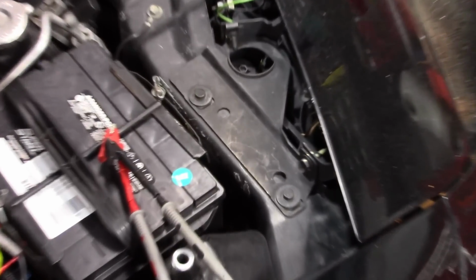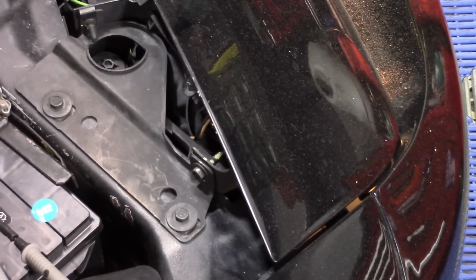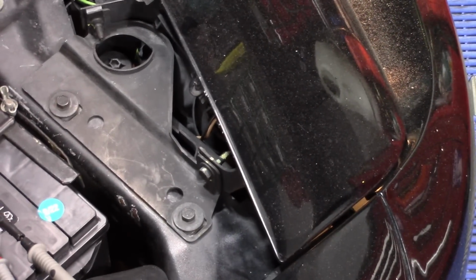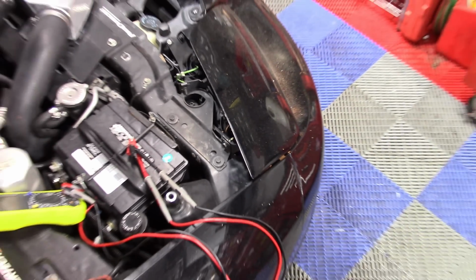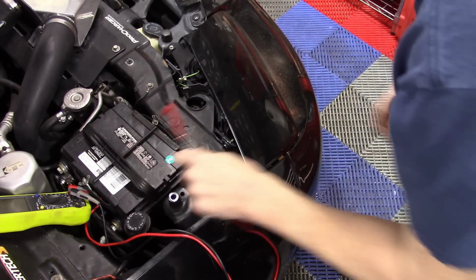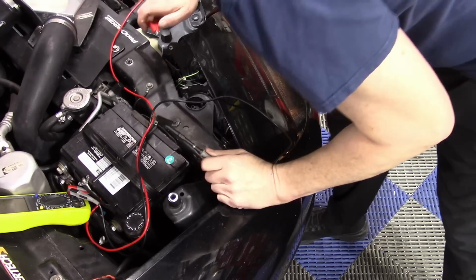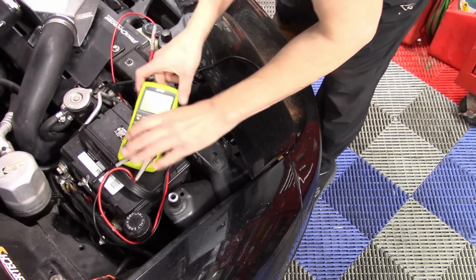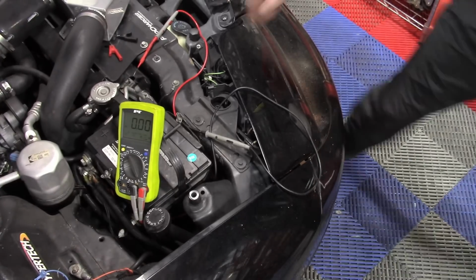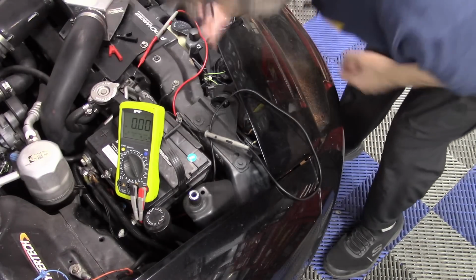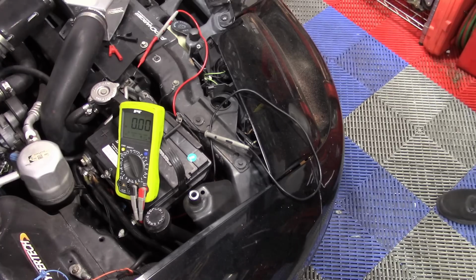Okay, it actually worked. If we look real careful, we can see some light from the headlight showing through. So the headlight is on now. I'm going to measure voltage drop across my headlamp bulb. What I'm going to do is take one lead of my multimeter. Let's get the multimeter in there. The easiest things to reach are going to be this brown wire and this black wire here. So we want to probe those.